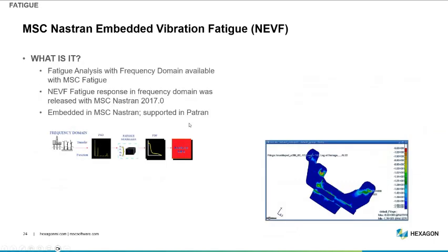And then something that's relatively new, still almost 10 years by now, is embedding fatigue inside of Nastran. So it's called NEVF, simply Nastran Embedded Vibration Fatigue. Now there's also transient analysis, it doesn't need to be vibration only. So this says we've got a mesh, and all the information that I would have usually added to a subsequent fatigue calculation, I directly add to Nastran to directly calculate the fatigue life.